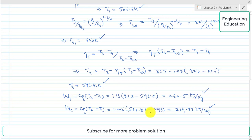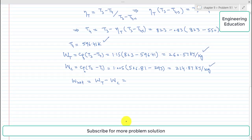Now to find the net work, we will take the difference of these two terms, which is turbine work and compressor work. So turbine work is 260.57 minus compressor work is 214.87. So simplifying this, we get 45.7 kilojoule per kilogram.